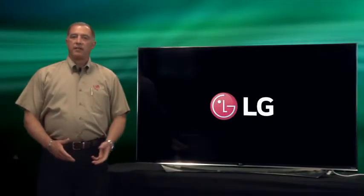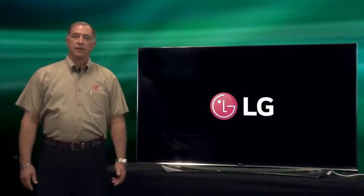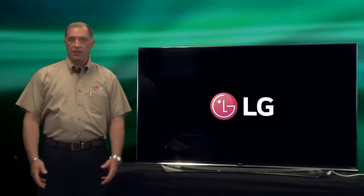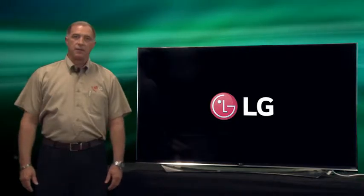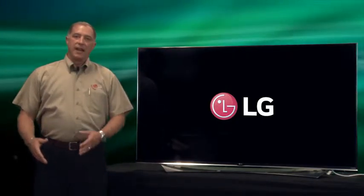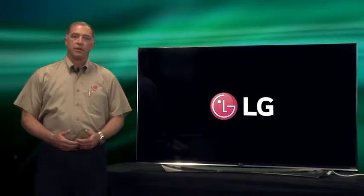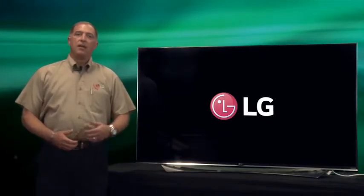What we're going to briefly discuss is some of the changes in the backlight controls that you'll see in the 2015 models, because the voltage and the response of the inverter has changed for the most recent models versus previous models that you've worked on before. The backlight circuit, each bar of backlights or group of backlights, has its own individual return to ground, which is brought up in the information that we've discussed so far.